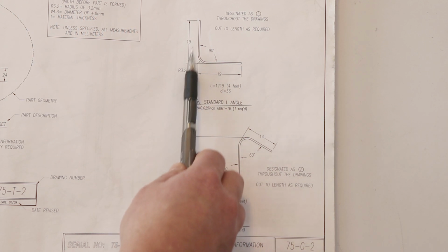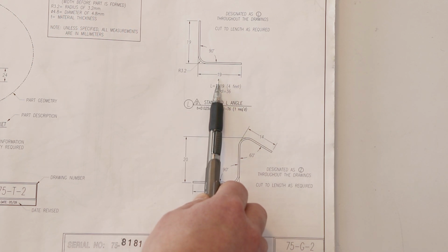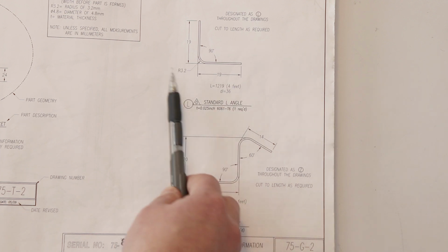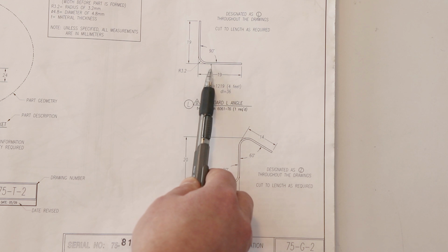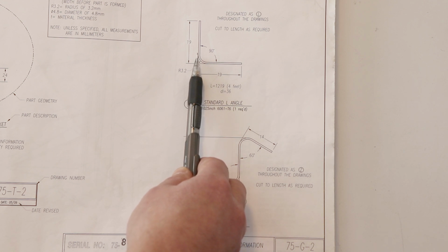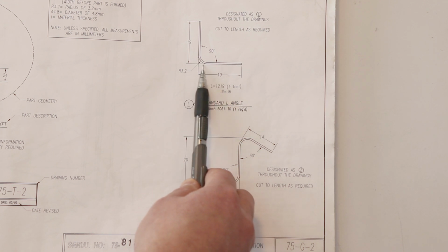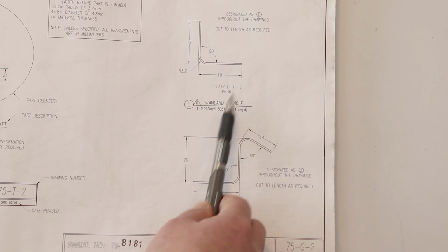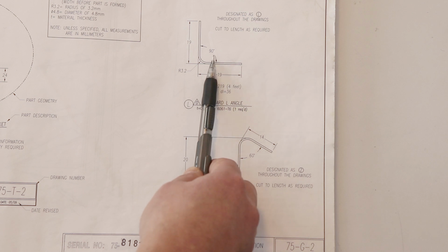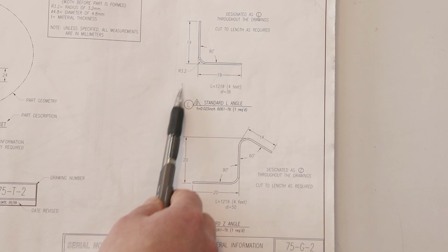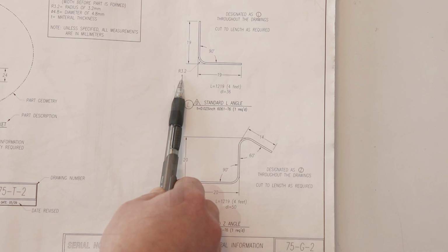Now you notice when this is formed, it's 19 millimeters on a side. Well, 19 millimeters times 2 is 38 millimeters. Again, because this gets formed around a radius, which is a shorter distance than a hard right angle bend would be, we start out with 36 millimeters. Once the part is formed, it ends up being 19 millimeters on a side, bent at 90-degree angles with a 1/8 inch radius or 3.2 millimeter radius.